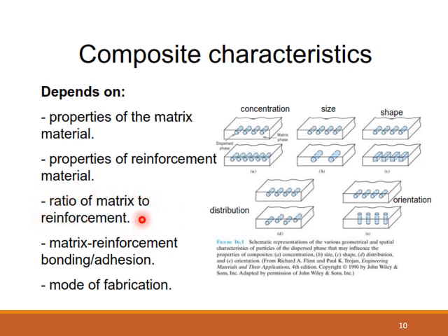So usually in the design of a composite material, you want to have an optimum combination of the two materials. So take for instance, if you want to design a fiber reinforced composite. What it means is that there is a particular combination of the two materials that will give you the optimum property. So what you need to do now is you need to play with the combination until you achieve this optimum property. So say for instance, you have a ceramic material, you want to toughen it with a fiber reinforcement. You cannot just decide that, okay, I will put in a volume ratio of maybe 0.2 fiber in 0.8 volume fraction of the matrix, and then you stay there. If you do that, you are not sure if you have attained the optimum property.